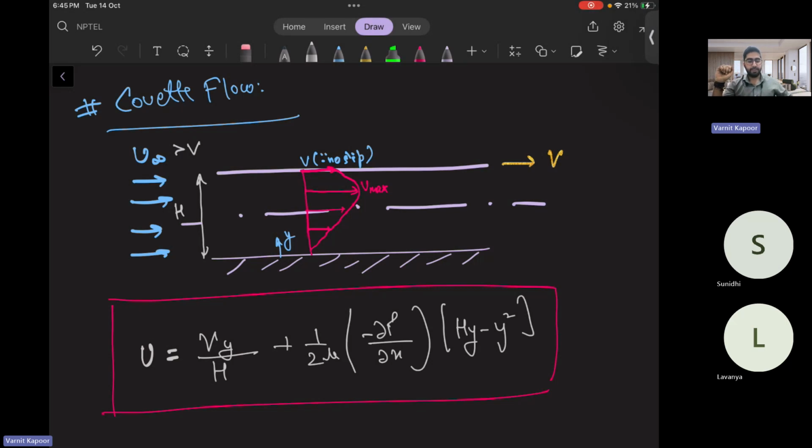So as I told previously, the mean velocity concept is not for momentum or kinetic energy calculations. But what if you want to incorporate the mean velocity concept? We should come up with some correction factors which should be multiplied with the mean velocities so as to get the exact momentum and kinetic energy values.